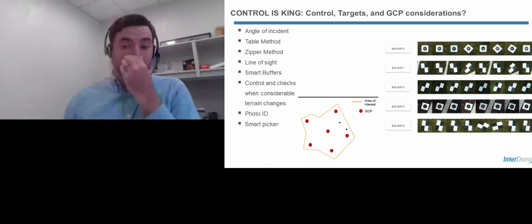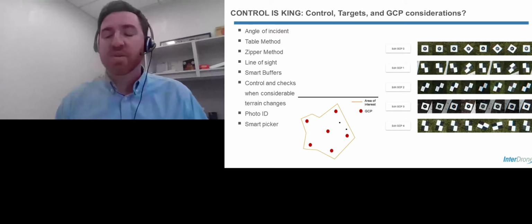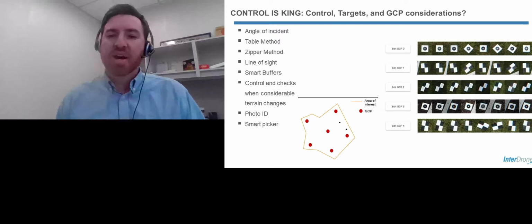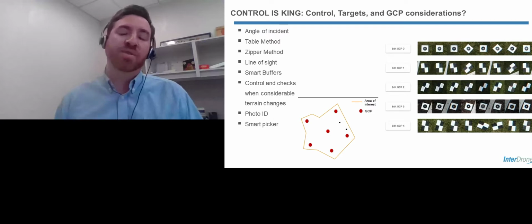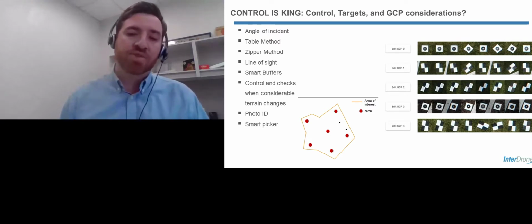All right. So just some more examples of control points. Here you're seeing more imagery-based control. The ones with the white squares and the black circles are pretty close to the ones that we're using for our drones now, both for photogrammetry and for our LiDAR acquisition.